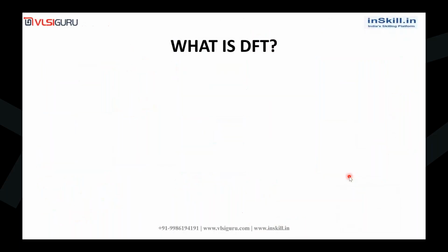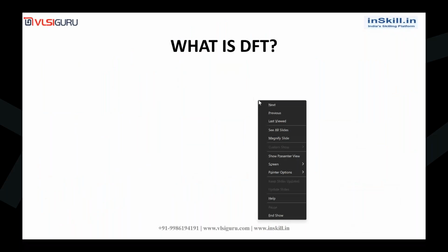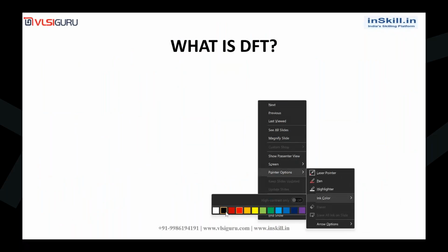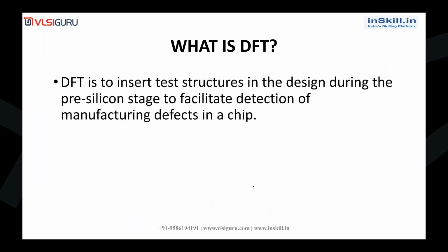So what is DFT? DFT is actually to insert test structures into the design. We will be inserting our own test structures in the design, like scan insertion, MBIST insertion, boundary scan insertion. Like that, we will be adding our own test structures in the design during the pre-silicon stage.